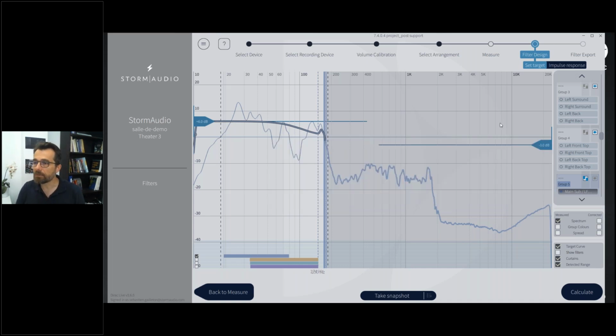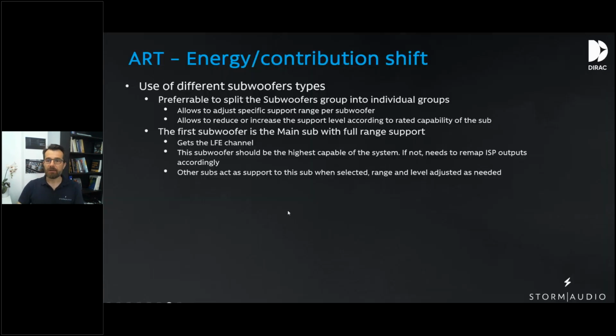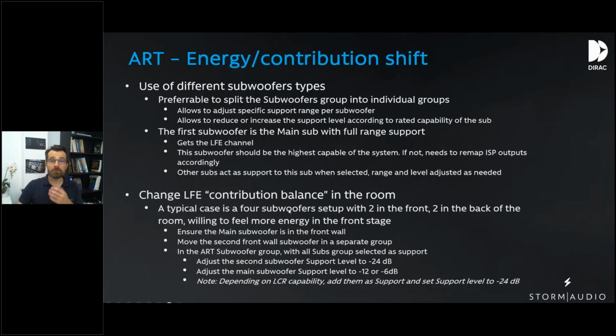So that's one use case where you want to split your subwoofers individually to make sure that they are with the correct characteristics. The other use case where you want to shift the energy is where you want to have a contribution balance that is different in the room. So a typical case is with 4 subwoofers, where you want to have maybe more energy coming from your front wall and less from the back wall.